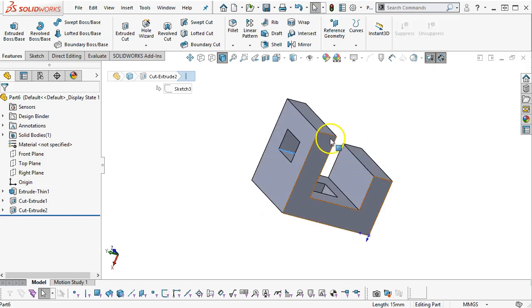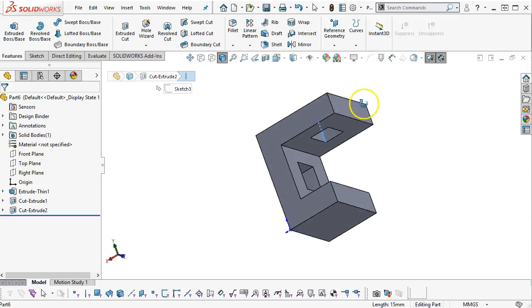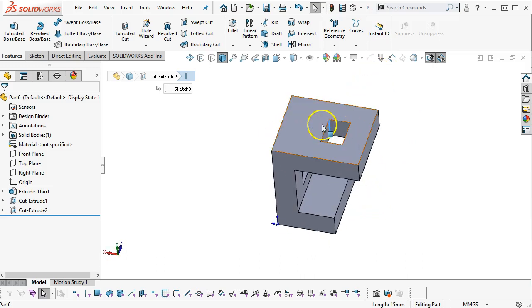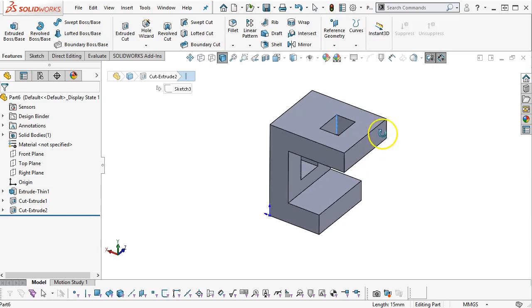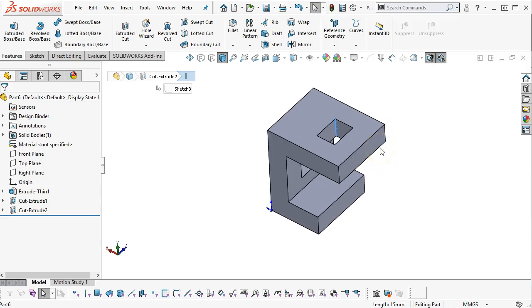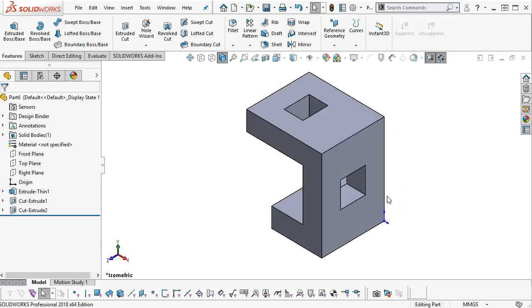So being that this is 15 millimeters, which is about 590, so call it 600,000ths deep, even putting an 1/8 inch radius in there, 1/4 inch would have no problem. A 1/16 would be a little bit of a challenge, but doable, and increase the manufacturability of the part by quite a bit.